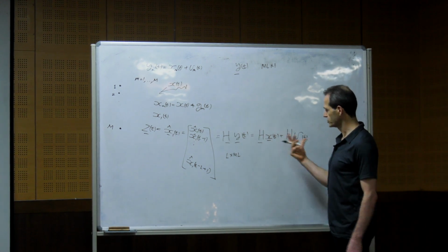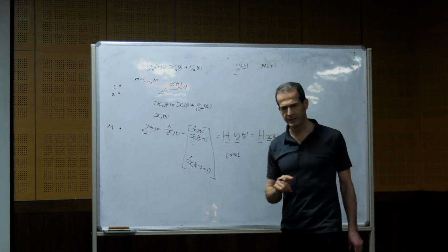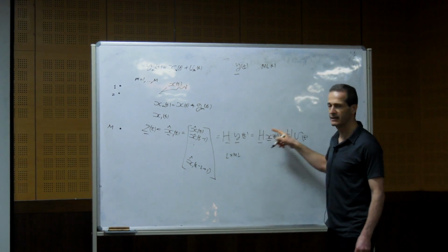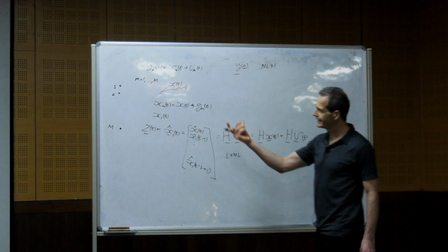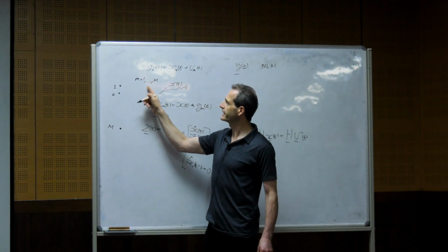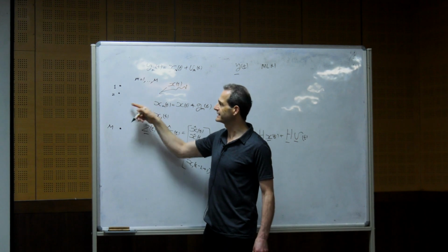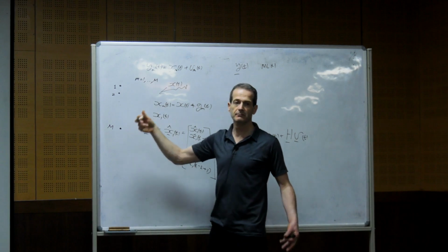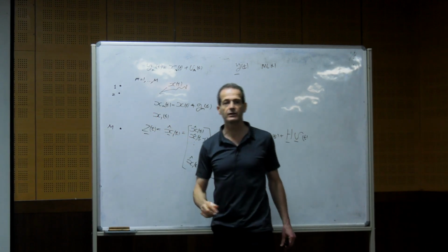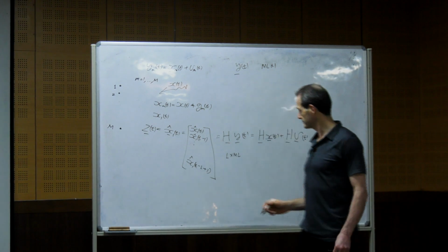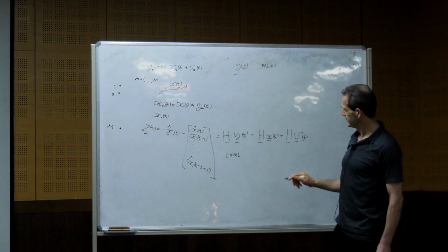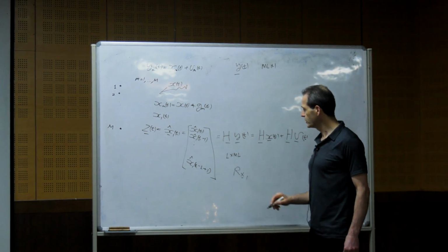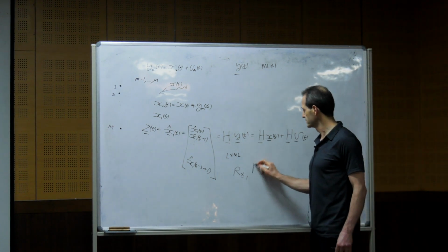Of course, we don't know each one of them, but we assume that we know the correlation between any sample in this vector to any sample in this vector. So within the L samples, we can take any sample from any sensor and find the correlation to any sample from the same or any other sensor, which is a lot of information, and we call it R_x, and we know the same information also for the noise, R_v.